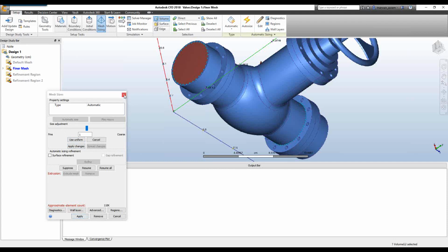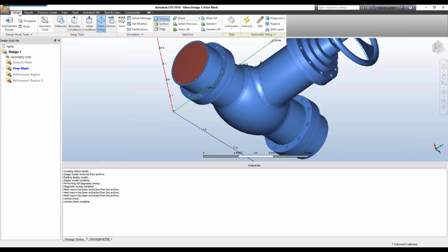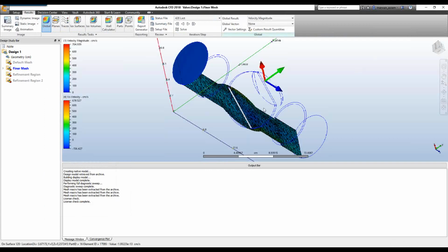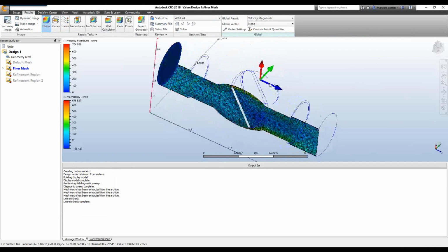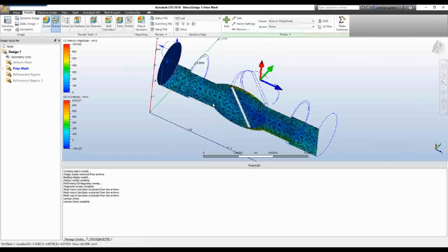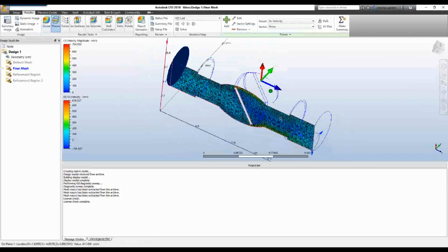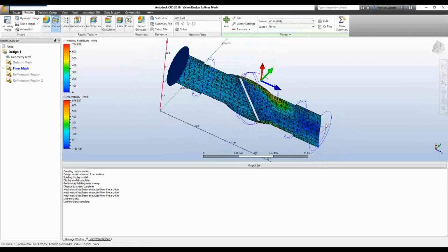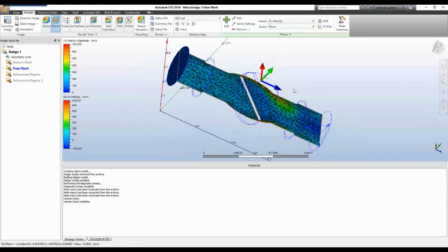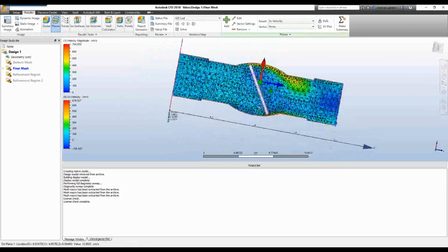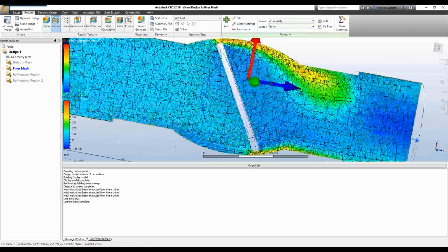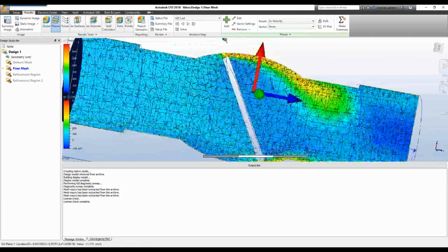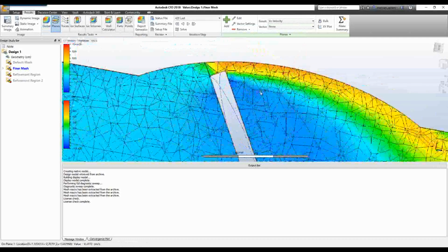And that gave me a little finer mesh, maybe a lot finer mesh actually. This is this mesh here. Let's move the plane up a little bit. That's my mesh here. Obviously, I get more elements. I have a table here to compare the results.